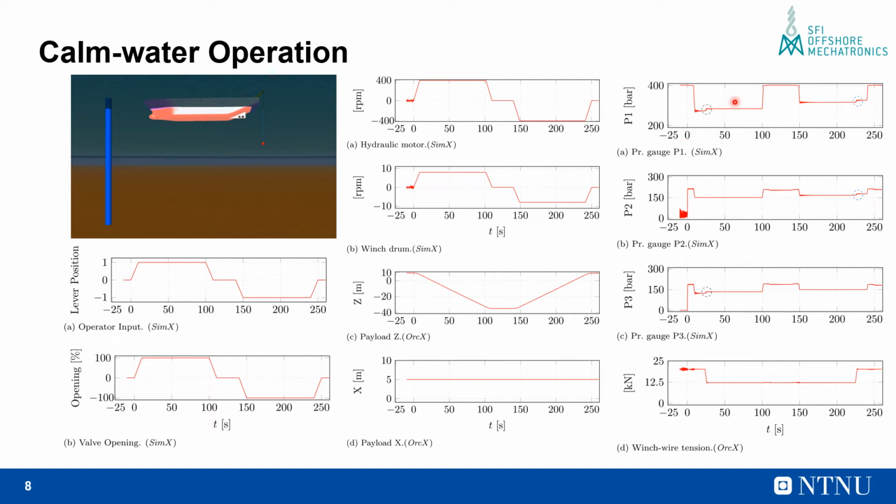As it is fully submerged, the pressure remains constant, and once it reaches the predetermined depth and the valve is closed, we see that the pressure climbs to 400 bar. At 400 bar, the bypass valve opens, and so the 400 bar pressure is maintained in the system. Again, as the valve is opened in the negative direction, we see that the system pressure drops. It continues at a constant value until the load begins emerging from the water, and now the full weight of the load acts on the winch drum, and again we see a slight increase in the system pressure.